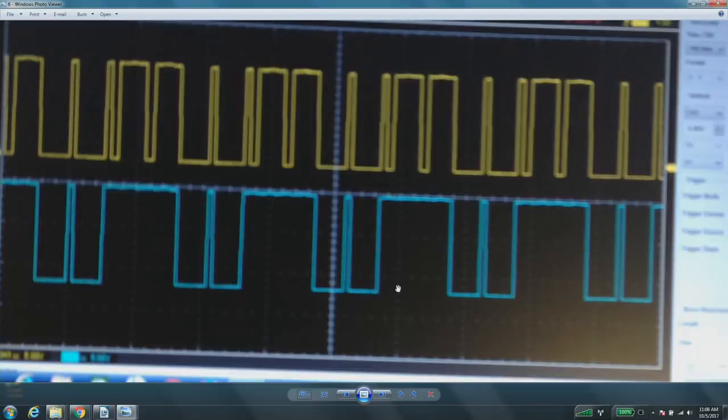So at this point, I suggested to Mike to grab a borescope, pull out the cam sensor, which is on the back side of these motors, and stick a borescope in there and take a look at what it looks like. Because something here is not giving us our proper signal. And he also mentioned that he swapped his cam sensors from side to side and the signal remained the same.